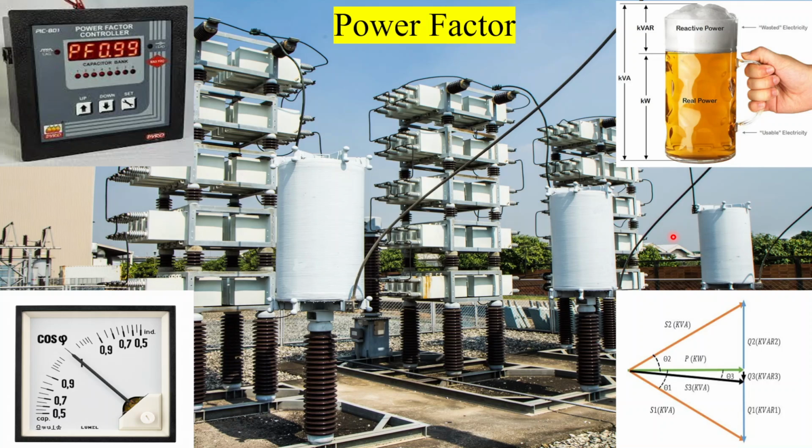A high power factor means reduced power losses in the electrical system, a lower electricity bill, and less strain on the electrical infrastructure. Consequently, many power companies charge industrial and commercial customers a penalty if the power factor falls below a certain level, encouraging them to implement power factor correction measures.